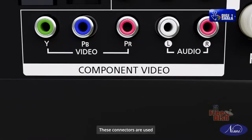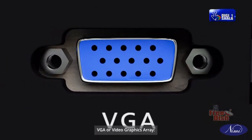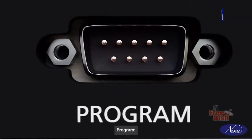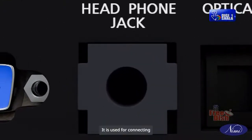Component Video. These connectors are used to transmit high-quality analog video signals, typically in the form of YPbPr or YCbCr signals. Optical Audio Out. This is used to connect TV sound to a home theater or soundbar and gives the best sound clarity. VGA or Video Graphics Array. This is used for compatibility with computers, gaming consoles, and TV. Program. This connector allows for serial communication, including firmware update, remote control integration, etc. Headphone jack. It is used for connecting wired headphones.